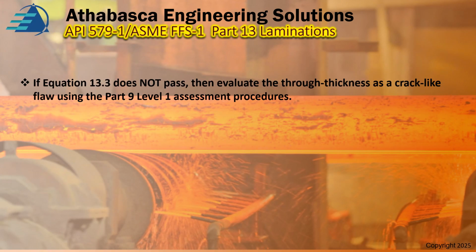I'd like to mention a couple of things about equation 13.3. If it does not pass, then we need to evaluate the through thickness as a crack-like flaw, and then we should be going to Part 9, Level 1 assessment procedures.